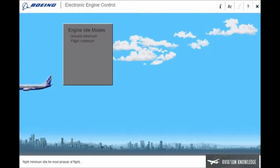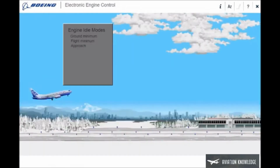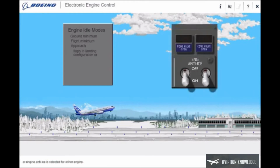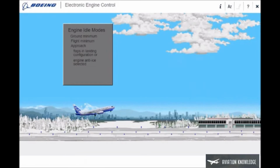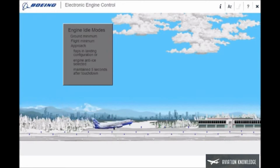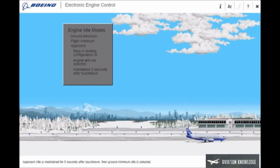Flight minimum idle for most phases of flight. And approach idle in flight if flaps are in landing configuration, or engine anti-ice is selected for either engine. Approach idle improves engine acceleration time for go-around. Approach idle is maintained for 5 seconds after touchdown, then ground minimum idle is selected.